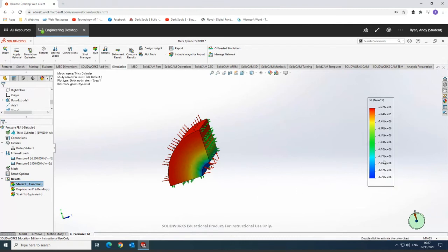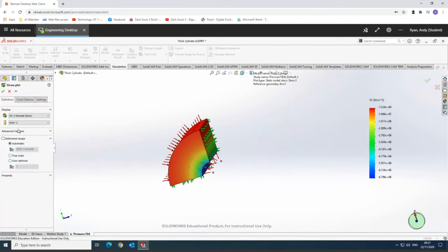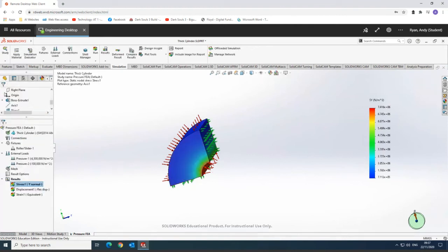Okay, these are all negative. Okay. If we do the same test on the stress in the y direction, now what we should be able to do is it should still be on that axis, which it is. You'll see all these stresses are positive, with the biggest stress on the inside. So I would suggest that's the hoop stress, and the stress in the z direction